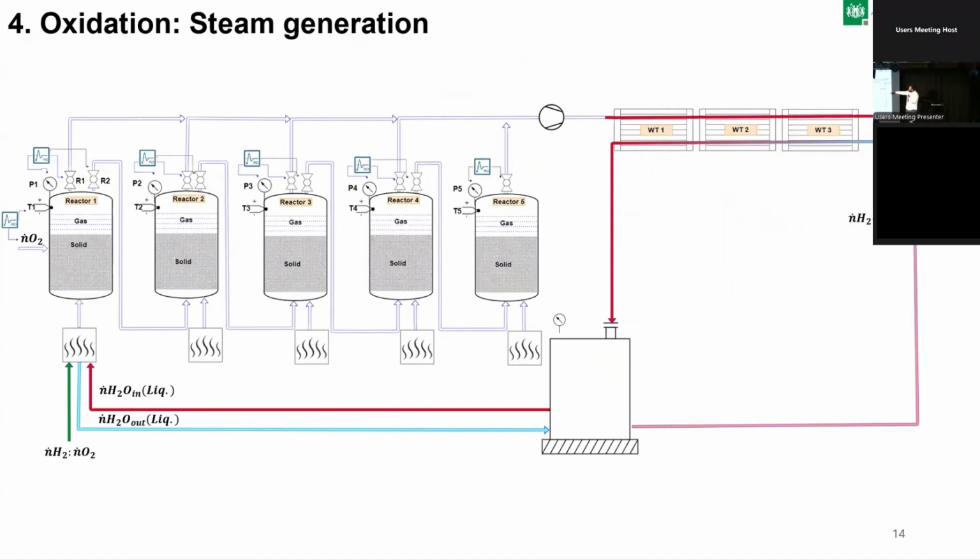This evaporator is connected to a liquid tank, which stores the liquid heated by the process gas. The user-defined evaporator also has a controller which controls the amount of hot water taken from the liquid in order to achieve steam at a desired temperature and pressure. And if the water is not enough, we add some fuel to it.